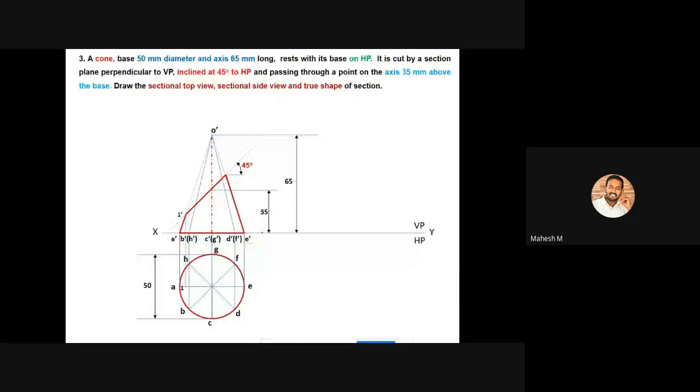So what is the procedure? We have to project all the cutting edges towards the top view. So initially you can project point 1 towards this one, which can be called O, the center point. So this particular cutting edge can be projected up to O to A, because it is available as A dash.